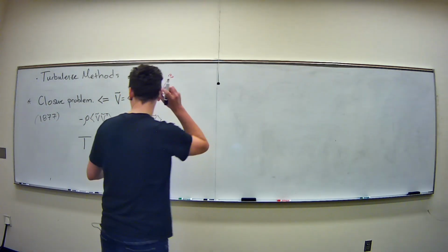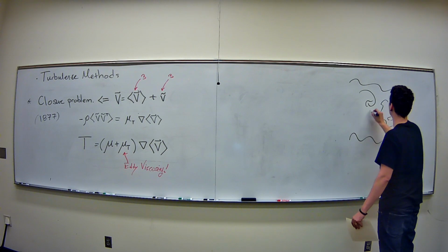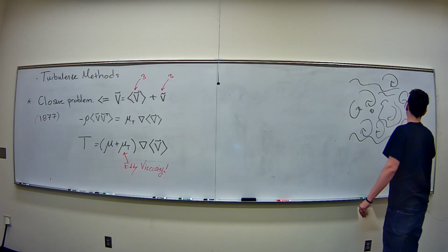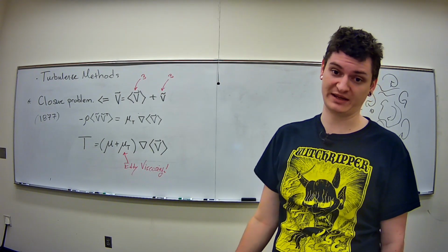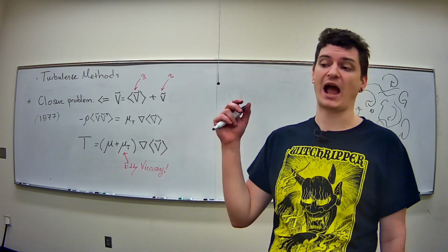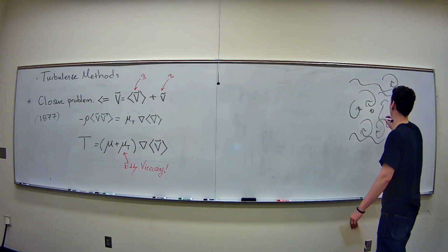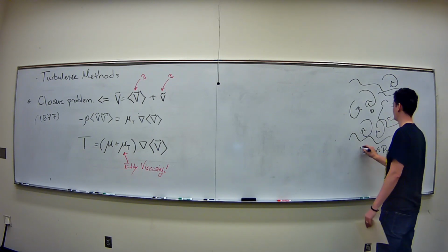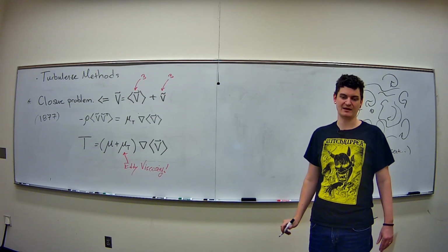Okay, so it's called an eddy viscosity because when you have these turbulent flows, it's just this wild sort of thing, and there's all these rotating things, certainly crazy stuff going on, right? So this is certainly what turbulence looks like, okay? And then there's this issue of what really is a good definition for turbulence, which is also really rough to get around, and people fight about that. So basically we characterize turbulence. Turbulence is certainly something that occurs where I have a large enough Reynolds number that everything goes haywire, right? So that's one definition. Another one is just this idea that the flow is highly rotational and there's the presence of these eddies. One way is eddies are present, being these seemingly little pockets of vortical flow if I look at a two-dimensional plane. So that's one characterization.